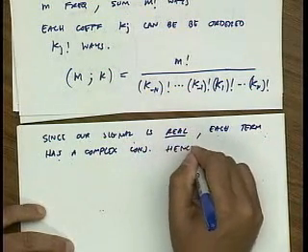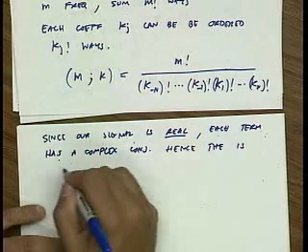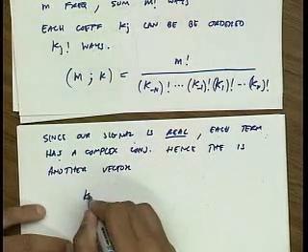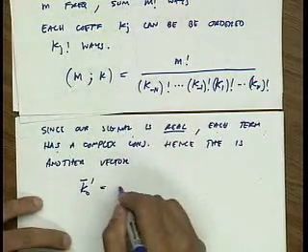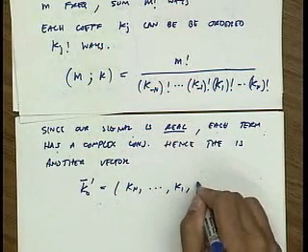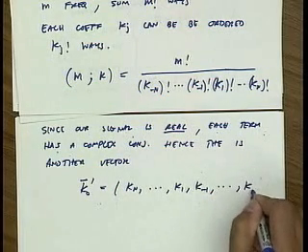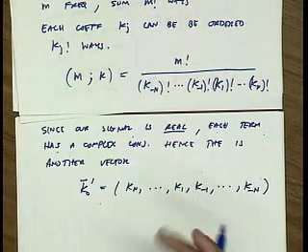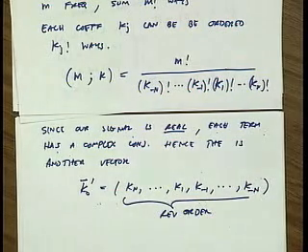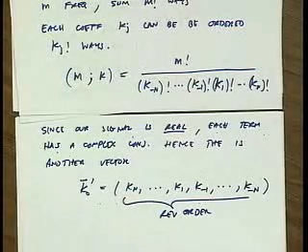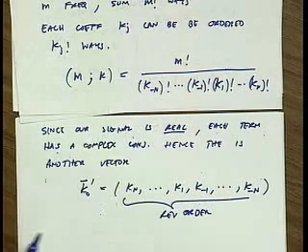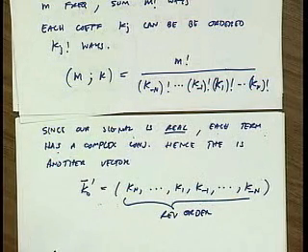So hence, there is another vector, let's say k0 prime, that looks like kn, k1, k minus 1, k minus n. In other words, it's flipped around, because the positive frequencies become the negative and the negative become the positive. So if I take this term and its complex conjugate, then I have a real frequency component.